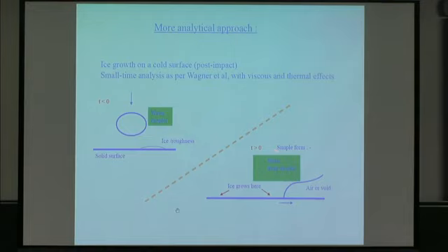So in positive time, the droplet comes down and the contact points spread out to east and west. This is looking at the eastward moving contact point. There's a westward one over there, and in this theory we deemed that the icing could grow anywhere in between those two contact points.